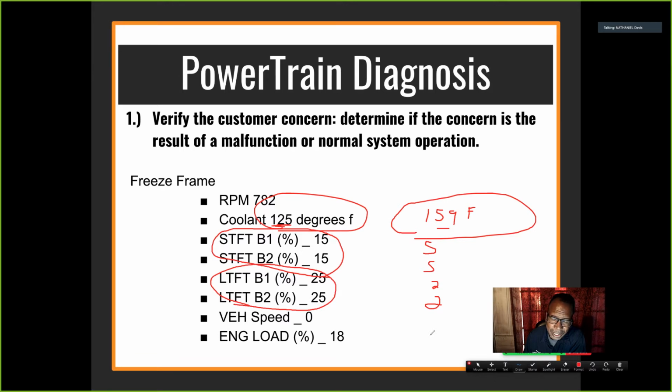The other three answers that I gave you will be there all the time. An intake gasket that's leaking, presuming it's a plastic intake, will seal up when it warms up. But they gave you choices of all of them being the right answer, so something in the question is leading you to the right answer. In this case, it was the temperature. A hose will always leak. Fuel pressure will always be low, and low fuel volume will always be low. It won't change with temperature. The only thing that would change with the temperature is the intake. So you're right, yes.